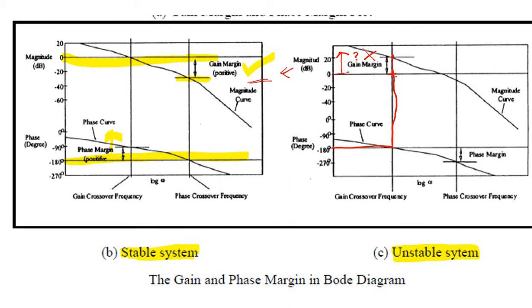And how about the phase margin? If we pull 0 dB here, down here, the cross section should be somewhere here. Whatever is okay. Let's say your graph is something like this. So pull down here, and that is actually your 180 here. And then you can see that, oops, the phase margin is below 180.